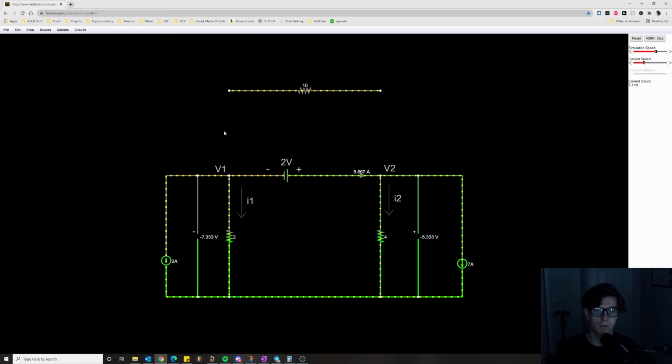Okay, so deleting them, like I said, it does nothing. The node voltages don't change at all. So I can put them back. Doesn't change anything. If you're wondering what it does change, pay attention to the current I measure through this that is being generated by this voltage source, and that's the only thing it changes.